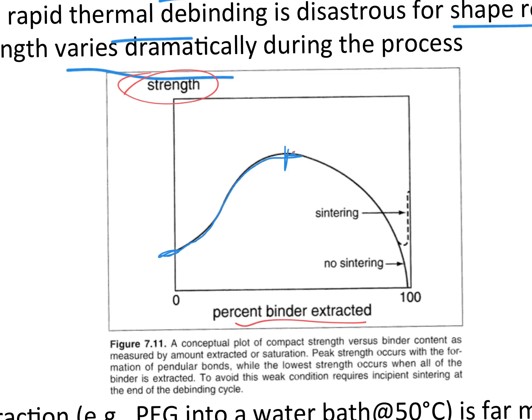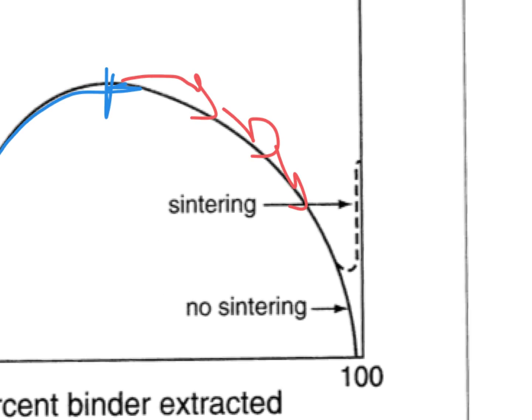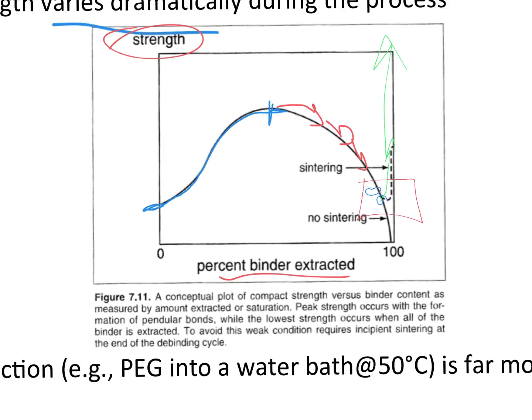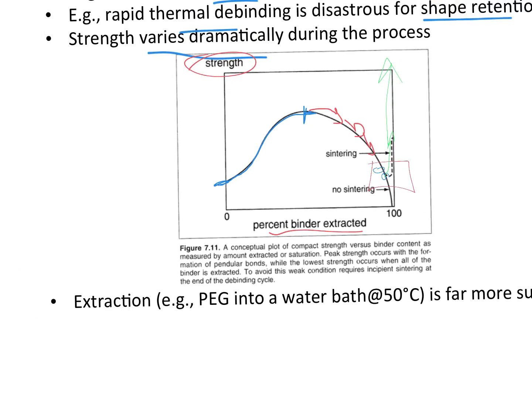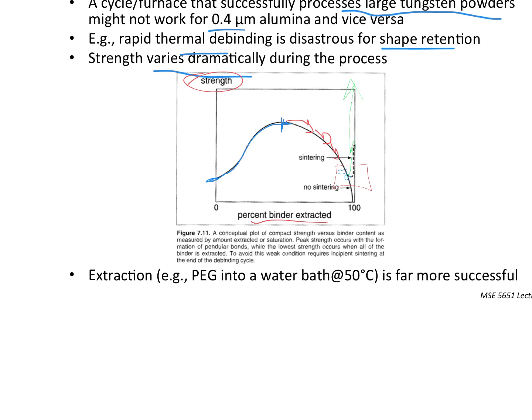And then from there we move on, and we're removing more and more of this, but what we need to see happen is this trade-off. The metal says, oh, I've got it from here, and the polymer turns into carbon, and then the metals start to sinter, and the strength goes up a lot more than what's shown here, because you're sintering it now, so it's much stronger in the end. But this area of trade-off between the polymer and the metallurgical phases needs to be controlled very tightly, otherwise your compact can fall apart. Okay, any questions about all that?